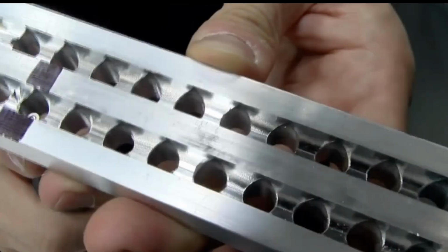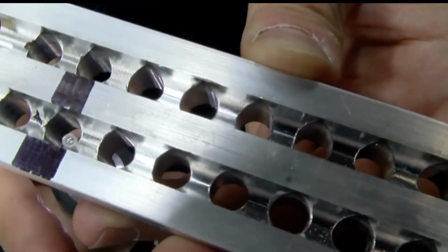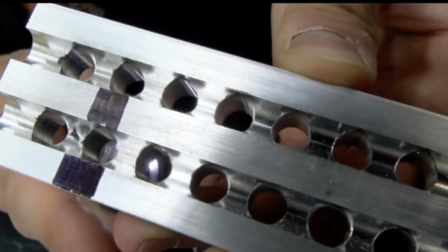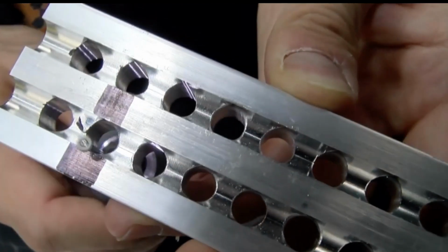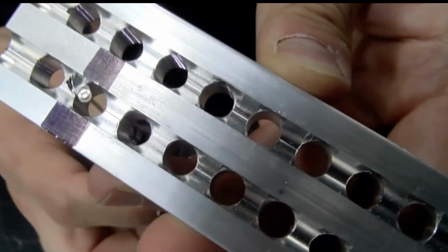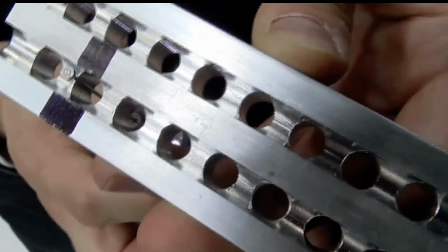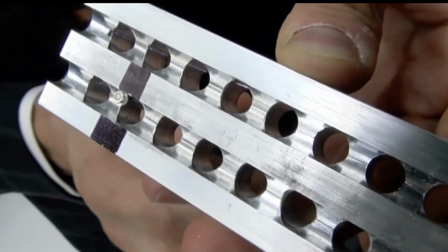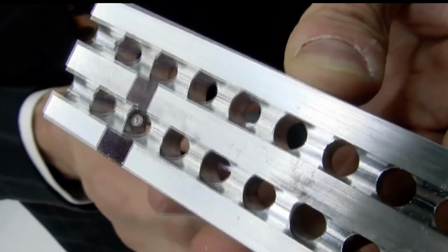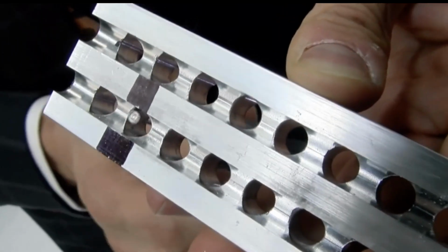Where are we? Here we are. I enter the hole. I don't do any damage to any of the wall surfaces. This protective ring is protecting all of the walls, and it's only when I come into this edge that I cut the burr. And the more time we spend there, the burr is gone now. The more time that we spend there, the more of the larger radius that we're starting to generate.